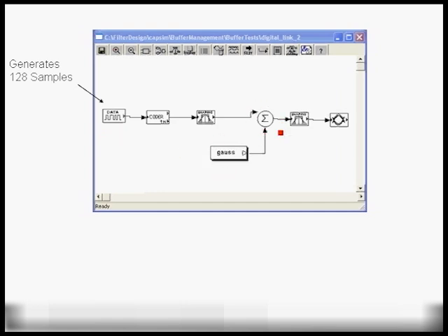So when we look at the add block here, on this connection it sees 8 times 128 samples, but over here, on the first visit to the Gauss block, it'll only generate 128 samples. So the add block will consume only 128 samples from the Gauss block and the 128 samples here, and output that to the output filtering block.